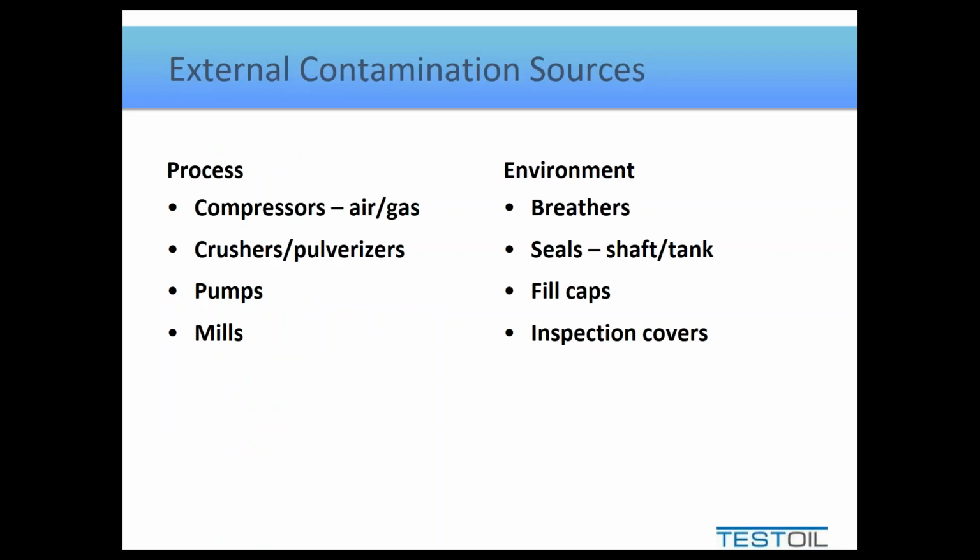Some pieces of equipment breathe more than others, and if they do so, they will definitely breathe in more particulate. But we also have, and why I put it first, is sometimes this is the overlooked side, some that are process related. What's the lubricated asset doing, and is it coming into contact with whatever we're trying to make it do? So compressors are a great example. As they compress air, the dust that may be in the air, and certainly the moisture that's in the air, can enter into the lubricant.